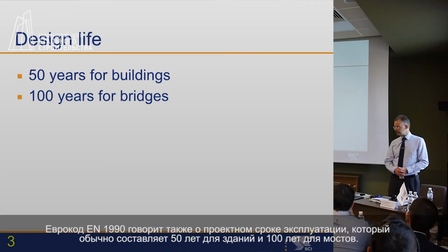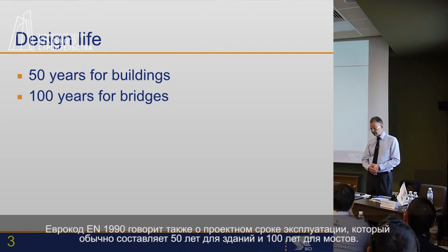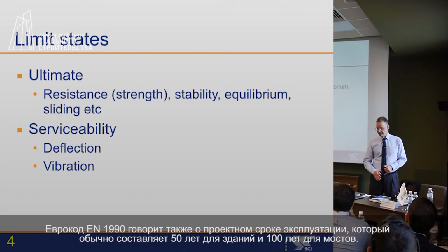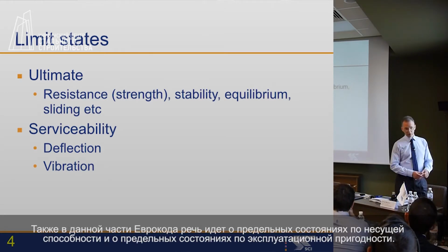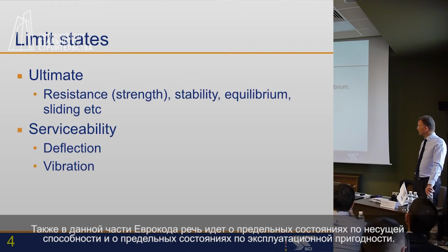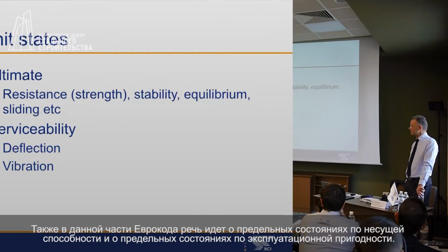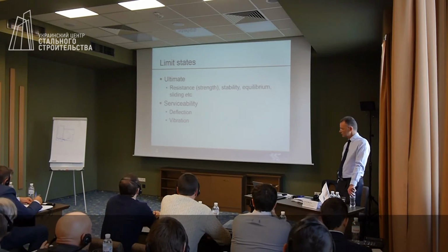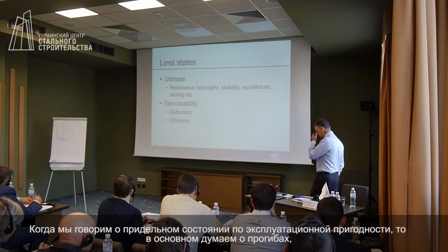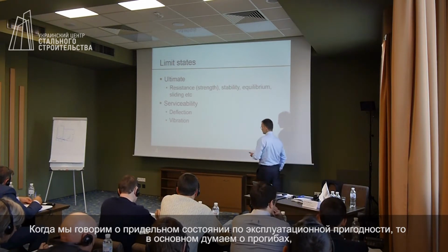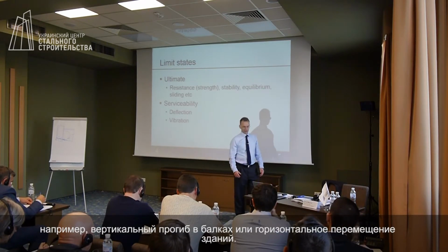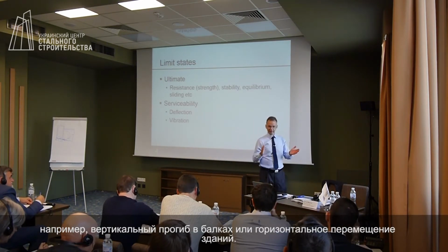EN 1990 tells us about design life, typically 50 years for buildings, typically 100 years for bridges. And it tells us about ultimate limit states, and it tells us about serviceability limit states. Serviceability limit states, we tend to think about deflection most of the time, vertical deflection of beams perhaps, or lateral deflection of buildings.